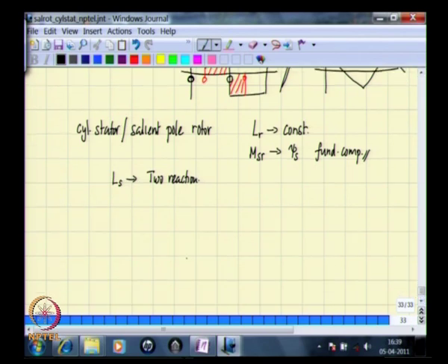Why have we done all this? Because we wanted to describe these electrical machines by suitable equations, and those equations are of the form: applied voltage is equal to the resistance multiplied by the current plus the rate of change of flux linkages. These flux linkages are dependent on inductances, and therefore unless we know the inductances you can't write this expression. So, in order to write this expression we have gone about trying to determine the inductances of various types of situations. We looked at simple situations first.